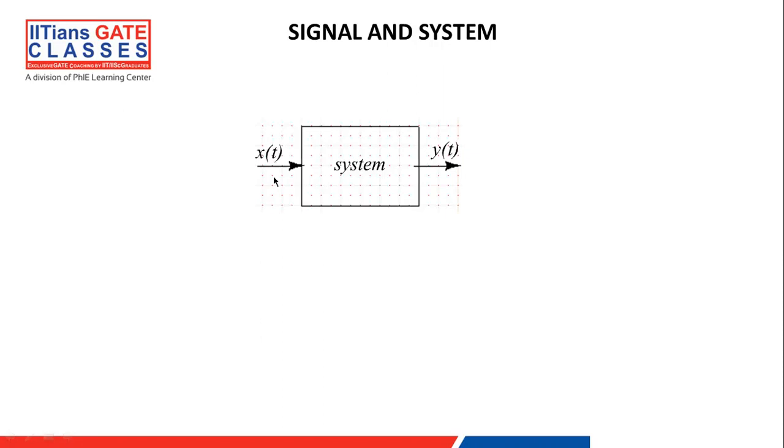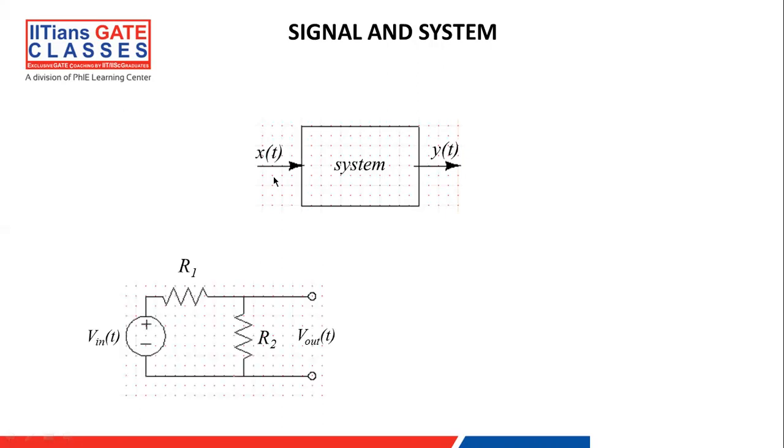Okay, so let's take an example of a very basic system. Let's see that this is a scenario where there is a voltage input, applied through this series resistor R1 and R2, and we are taking the output voltage across this resistance R2, right? If you apply some network terms like KCL or voltage division rule here, you will find that this voltage V out is nothing but this equation. So V out is nothing but R2 upon R1 plus R2 into V in, right?